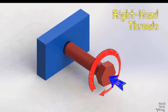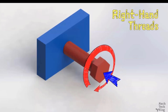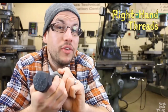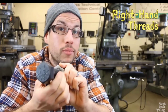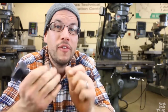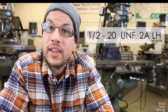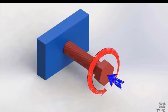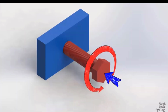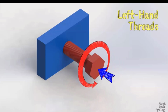For example, most threads are right-hand threads, meaning that they're made so that turning a part clockwise advances it into its mating thread. Typically, bolts and nuts tighten against one another when you turn them clockwise. You know, righty-tighty, lefty-loosey. But if you see an LH in the thread specification after the thread class, then this means that the threads are wrapped the opposite way, so that turning the part counterclockwise will advance it into its mating thread. These threads are called left-hand or reverse threads.